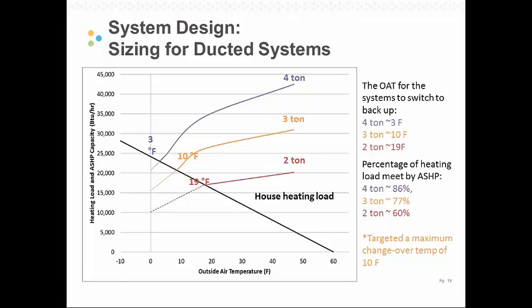And so what we see in that is that at negative 11 degrees outside, which is the design condition for the metro area, it takes about 30,000 BTUs to keep the house warm. And we can assume that somewhere around 60, you don't need any energy to keep your house warm. Somewhere between 60 and 70 degrees, people typically turn off their heating systems.